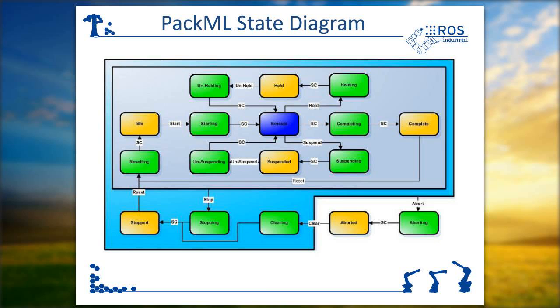These states are very carefully thought out over the last, I think it's 13 years or so of PackML development, and they all are useful and necessary for someone. They may not be useful for you, which is fine. You can have a state that literally just passes along to the next state, but they have to be there so that you can have the full state model represented.